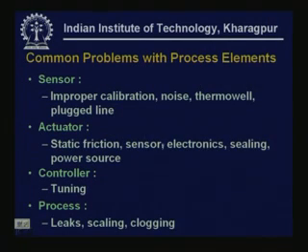Similarly, you could have actuator problems, various kinds of problems like friction due to lack of lubrication. Then actuators also have sensors, so there may be problems there. There may be problems of electronics or problems of sealing. Sometimes fluids will leak, say in hydraulic systems, or there may be problems of power sources. For example, suppose you have a pneumatic actuator and you have less air pressure, or you have a hydraulic actuator and your hydraulic pump pressure has fallen. Such problems cause problems in the actuator. These are very typical problems.